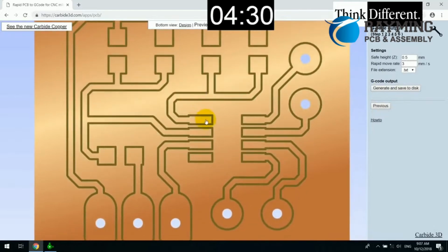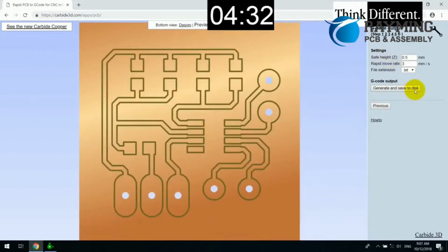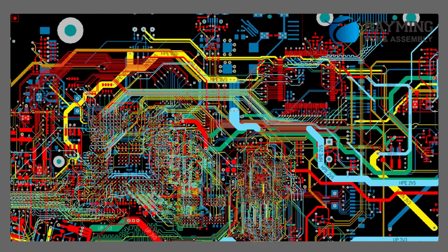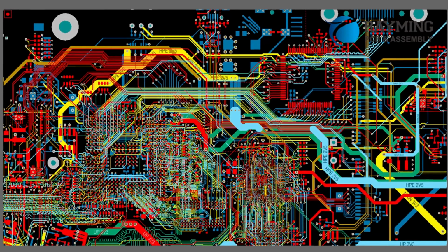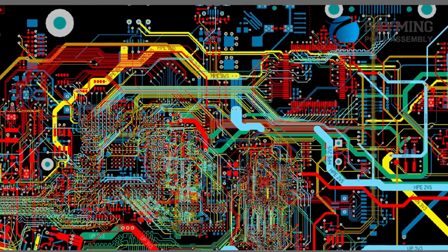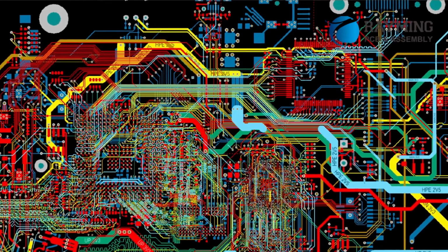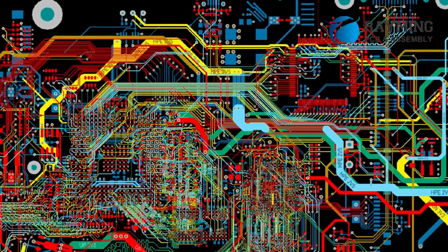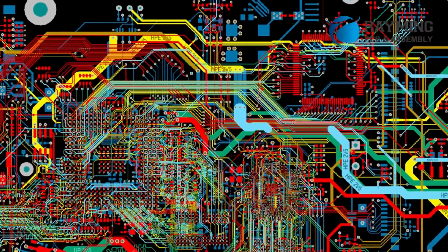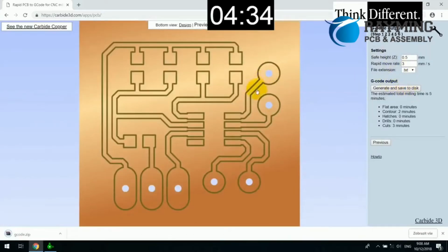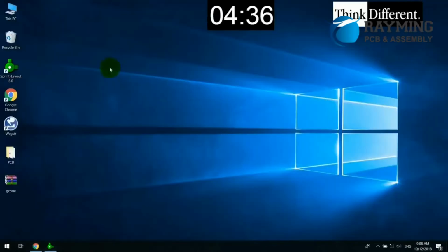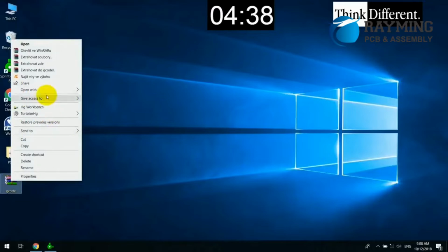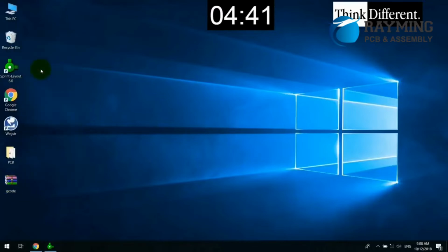When designing a PCB, you'll first want to decide the size of the board. The enclosure that houses your PCB will often be the largest limiting factor. Besides enclosure size, component selection can also affect the size of the board. For example, surface-mounted components have a low profile, so they can be made smaller. By contrast, through-hole components have larger footprints and are easier to find and solder.